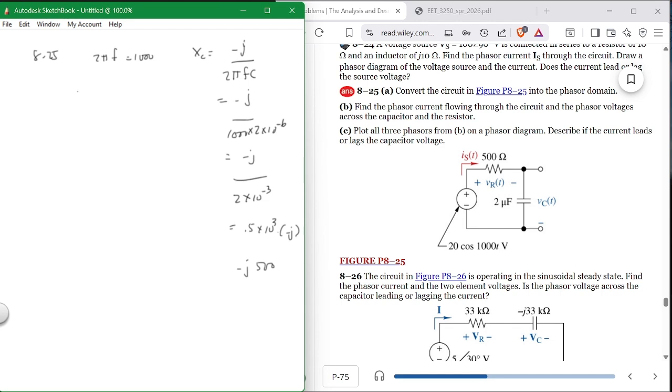So what do you use for your power or your voltage? You use the 20, okay? Now this is peak. But when you are given peak, you solve the question in peak. When you're given RMS, you solve the question in RMS, and you don't worry about it. Most of the time, this one is definitely in peak, but we don't care. We either solve it one way or the other based on what they give you, and this is all they do. So you solve it just like a DC problem.